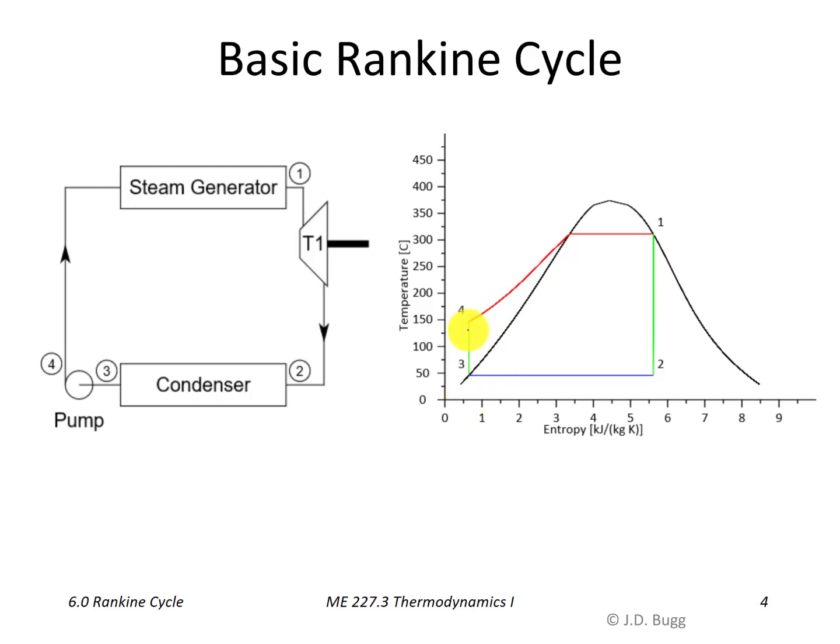little more clearly. So that's the big change from a Carnot cycle to a Rankine cycle, is the compression process moved into the liquid region and achieved with a pump. So notice this is no longer a Carnot cycle because our heat addition process now, which happens from 4 to 1, so 4 being the inlet of the steam generator, 1 being the exit, it's no longer happening at constant temperature. The temperature increases during this part of the steam generator, and then finally it's constant for the last portion of it. So it's not a Carnot cycle anymore because the heat addition is no longer at constant temperature.